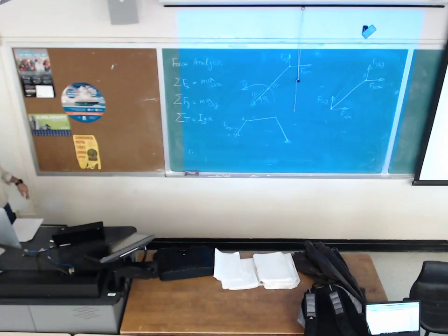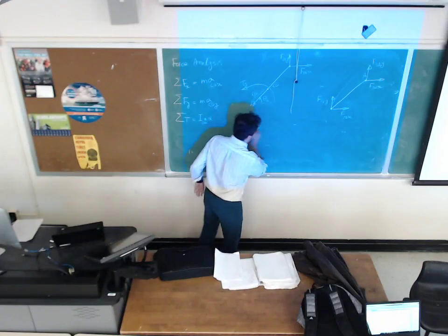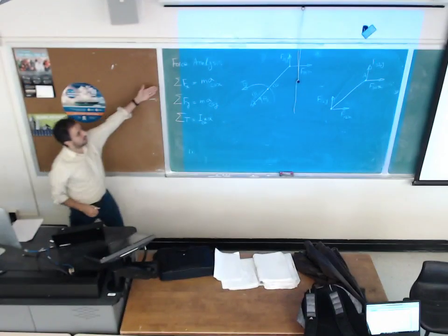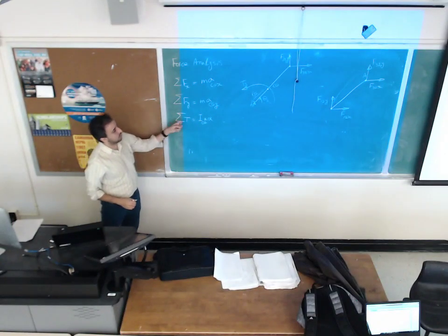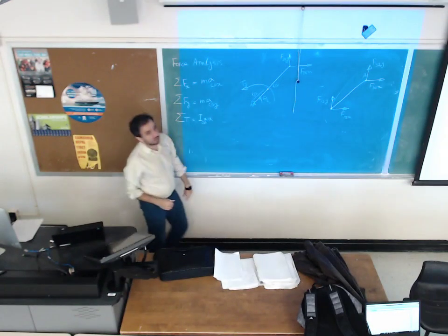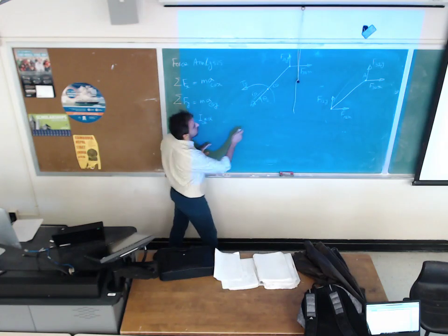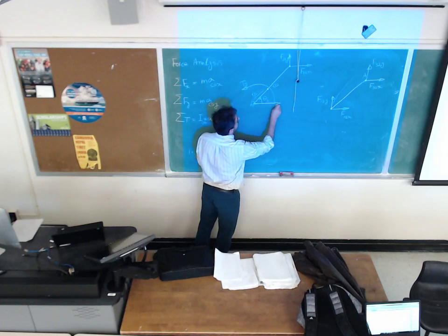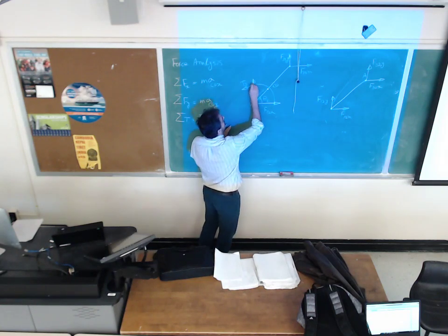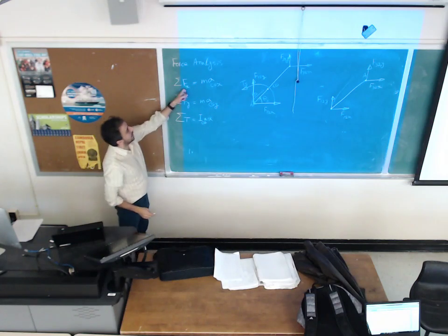So now we are ready to write these 3 equations, which are the equations coming from Newton's law for this single rigid body. Let me represent the force here, F12x, F12y. Summation of the force in X direction, set it equal to mass of link 2 times acceleration of center of gravity in X direction.